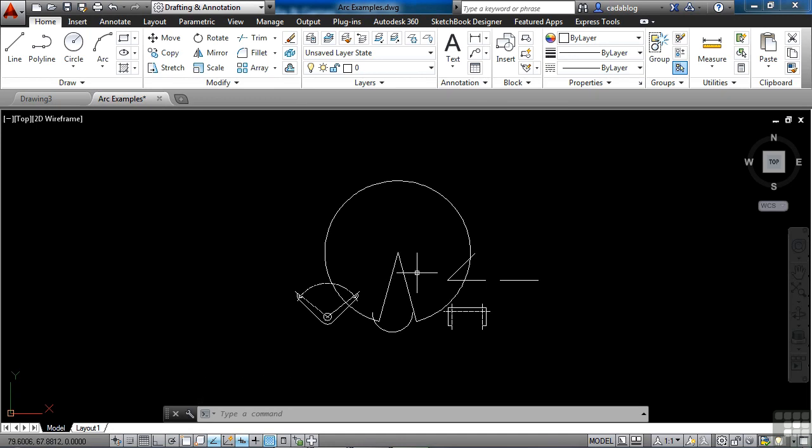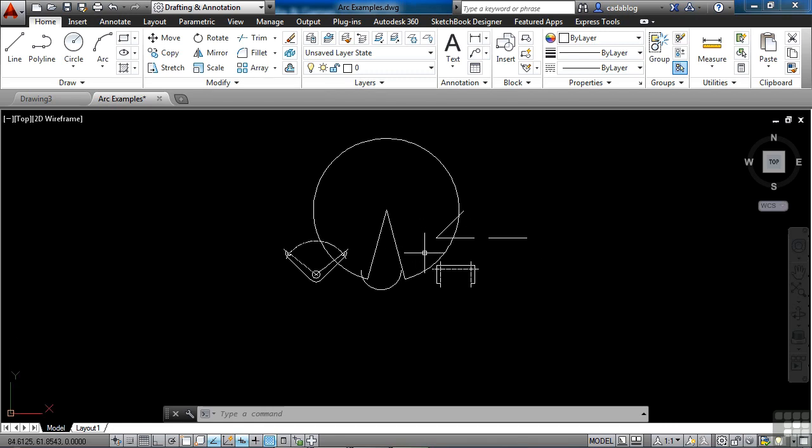This will make your first point the center point of the arc, and it will make you draw all sorts of arcs. So now you have 2 ways to draw an arc, from a start point to a point in between and then to an end point. Or now you can start at the center and get your start and finish points at that defined radius. Now, you don't always know these points. That's what's great about the arc command. The majority of what you're going to need for your arc command are the 2 that I just showed you.